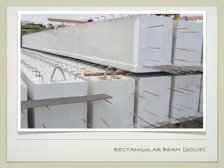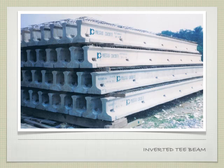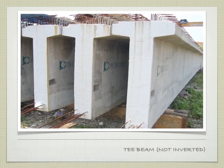This is the little loop that helps you pick it up and move it on a particular site. These are the reinforcing that are put in ahead of time. We'll talk about that reinforcing in a little bit. So they're pre-tensioning pieces. This is the inverted T. This is a T-beam that's not inverted. We know it's not inverted because we have all that topping or all the rebar sticking out the top, right?